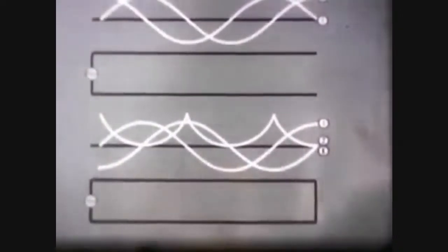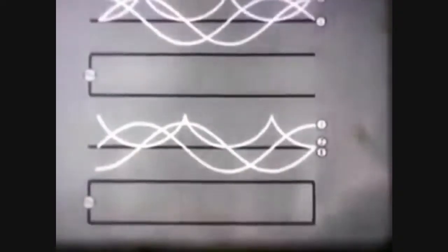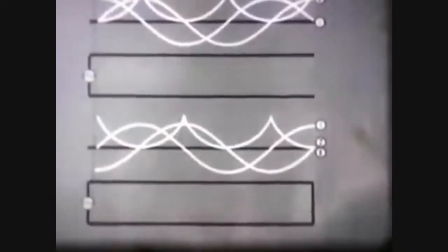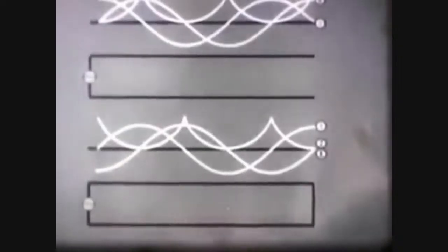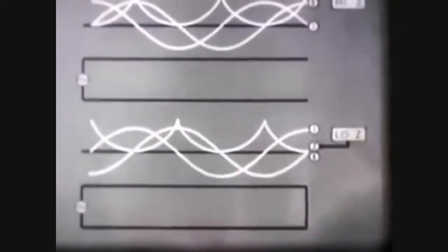Voltage at the open ends of the line is at peak point. Impedance at the open end is maximum. With the same frequency applied, a comparison of the shorted and open line shows that the curve values are reversed.